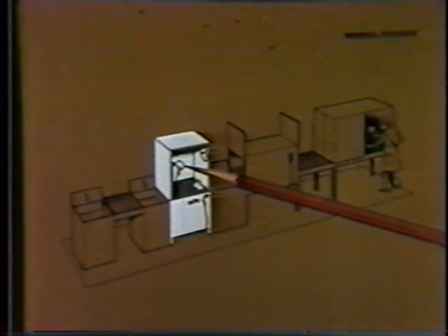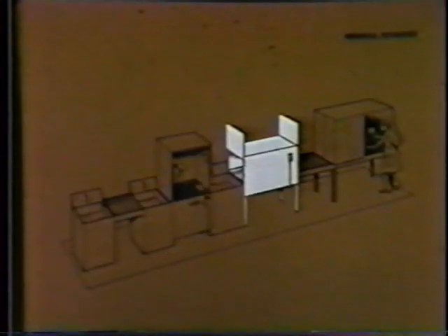Fluorescent systems include an overhead black light to aid in rinsing specimens. This setup shows a wet developer tank next, followed by an oven dryer. When dry developer is used, the two stations are switched. The dryer is located next to the rinse station. Next comes a conveyor or rest station, followed by an inspection booth. Depending on the type of penetrant, black light and/or visible lighting is provided in the booth.